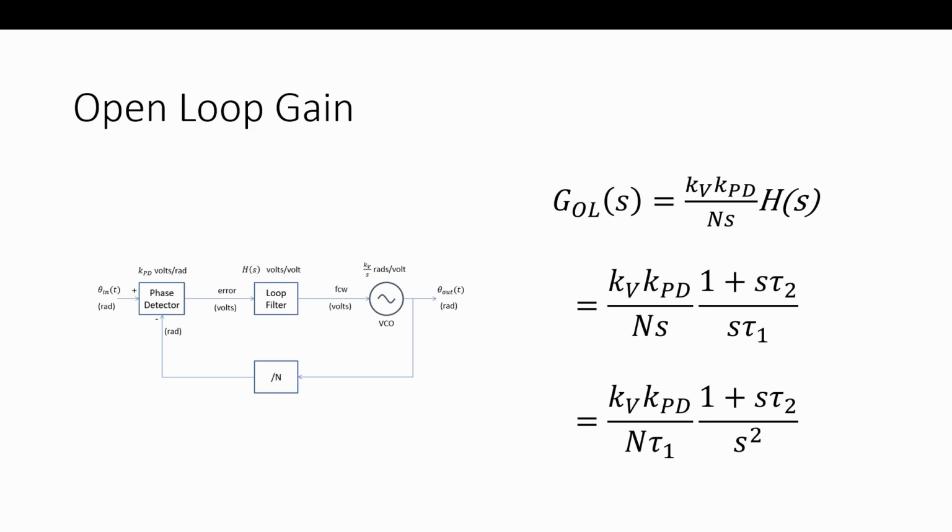It can be anything, because we can go into higher order loops. We could have a loop filter that's just proportional, which may not be a good idea, but we can have that. It can be just an integral, which wouldn't work in this one, it would go unstable. But we can have other loops where, if it was a frequency lock loop, notice we have two integrators in here. We have the integrator in the loop filter, and we have an integrator in the VCO because of the units we use, that 1 over s.